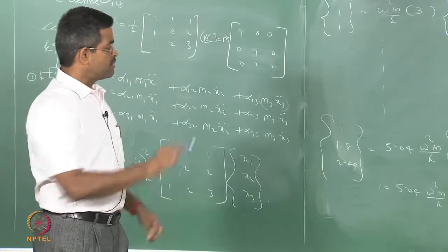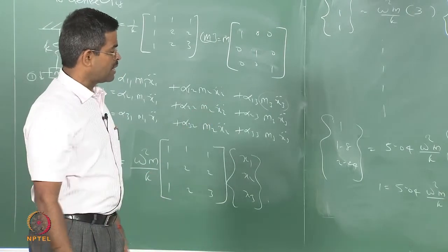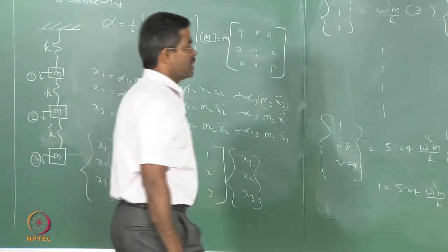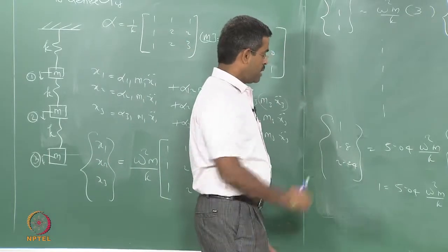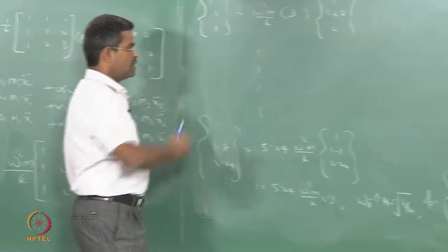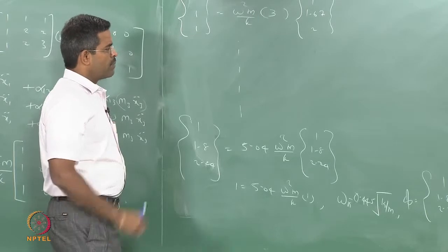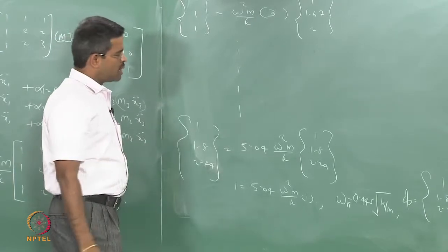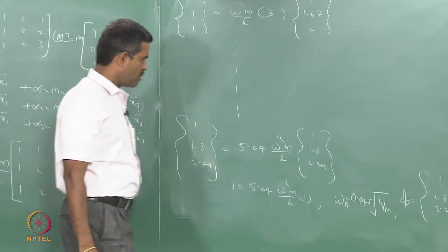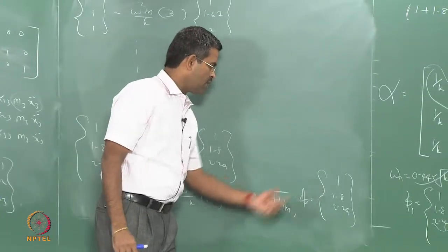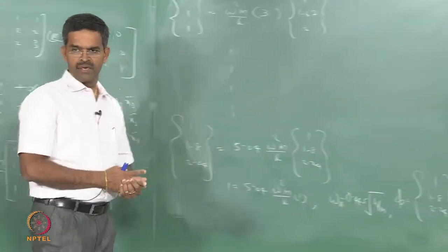That is a very interesting question, you have got to answer that, why Dunkerley is not focused on mode shape. The influence coefficient method and Stodola's law are comparatively matching, but Stodola's law is more popular because it focuses only on the fundamental frequency and mode shape, and its method is highly generic.